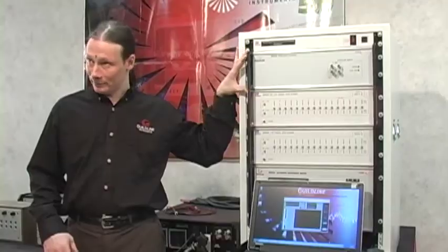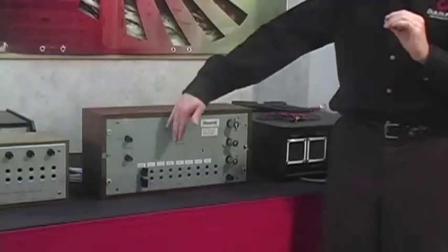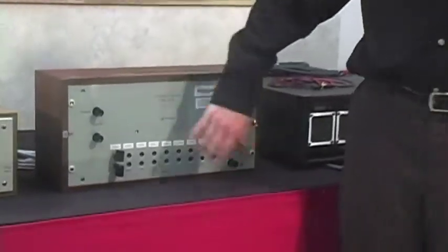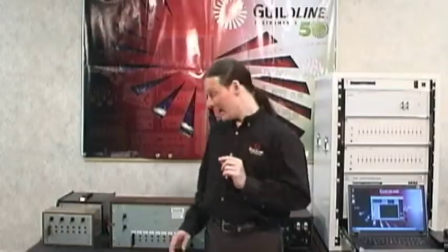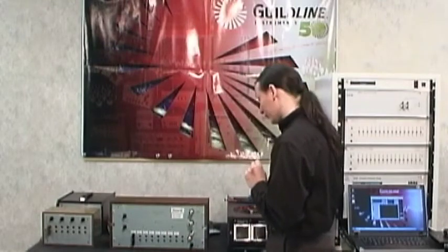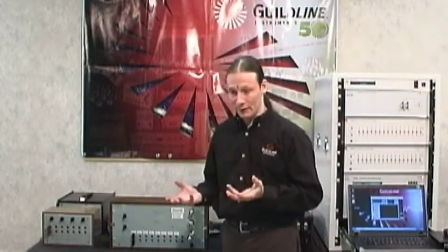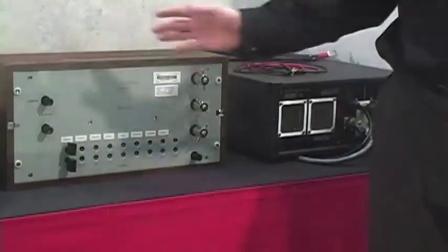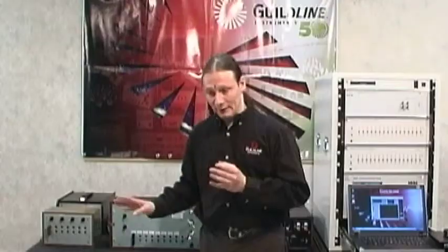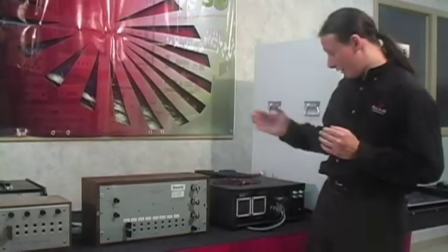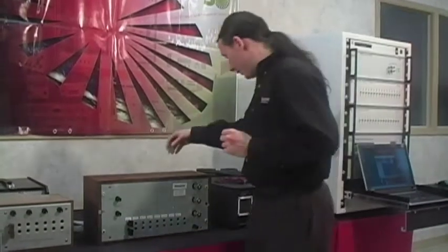and some of the higher value reference standards here. And then when you start getting down into the higher current values, where you're going below 1 ohm, in most cases you'll either be using a 1 ohm or a 10 ohm, and you'll be measuring with higher current through this range extender. And so there's multiple different setups that you're going to have to change the wiring and configuration to actually make it through one of these shunts. At least you will not have to determine all the measurement configurations through the software, as that will be automated for you. So to begin, you'll connect the shunt to a scanner channel that is free.